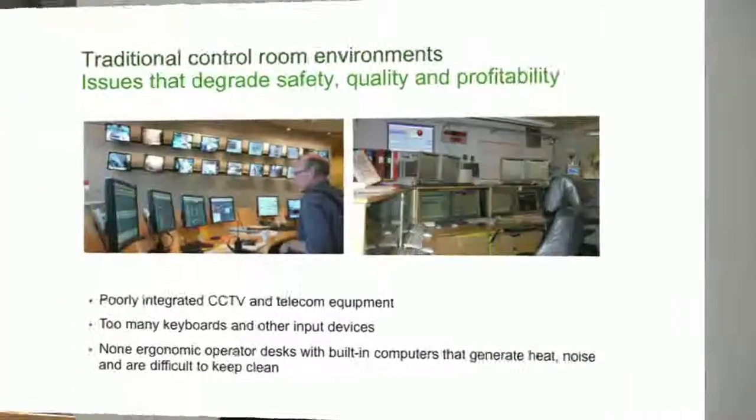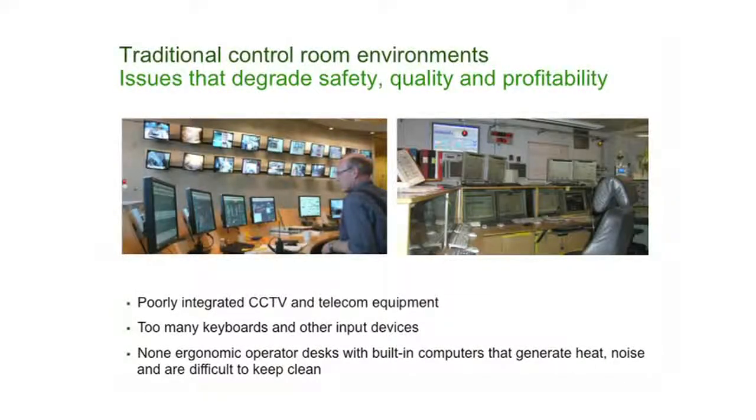What will happen is that he will get an alarm, and then he might want to look at something, but then he has no connection, no control. He cannot scroll back in time to see what did the camera see, or save off any of the video for later review. It's more there to impress on visitors in the control room, and also possibly for other people walking around, but not necessarily helping the operator. And that's what we also see as an issue. We need to change the way we are designing the control room, so we focus on the operator first and then on other people.